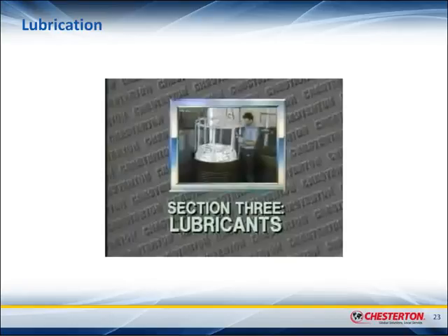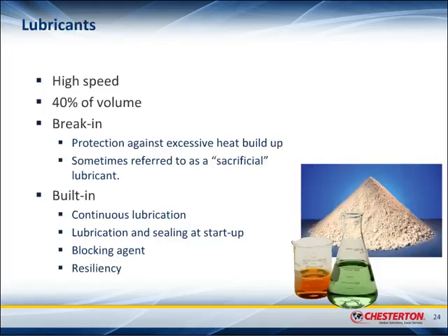They are suspended in water, and before braiding or after braiding, the fiber or the packing is pulled through this bath of PTFE, and the PTFE incorporates itself in the fiber or the braided packing. You basically cover either the yarn or the fibers or the packing with PTFE.